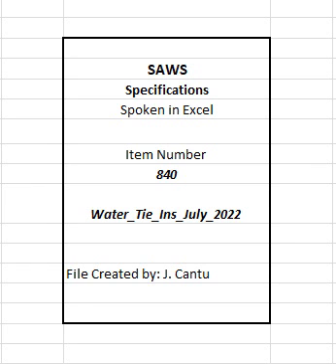840.3 Submittals. Contractor shall submit manufacturer's product data, instructions, recommendations, shop drawings, and certifications. All submittals shall be in accordance with engineer's requirements and submittals shall be approved prior to delivery. 840.4 Materials. The materials for water main tie-ins shall conform to the specifications contained within the latest revision of SAWS material specifications for all appropriate items.